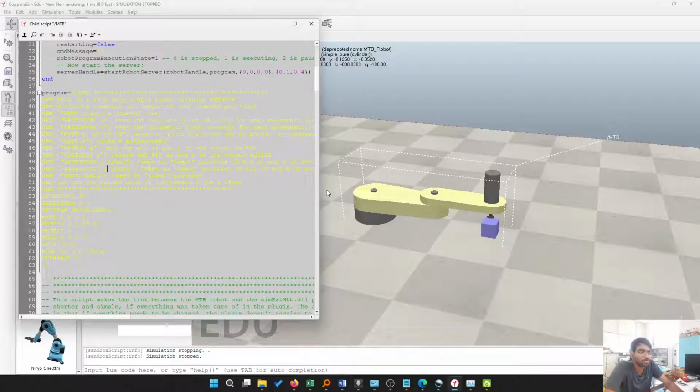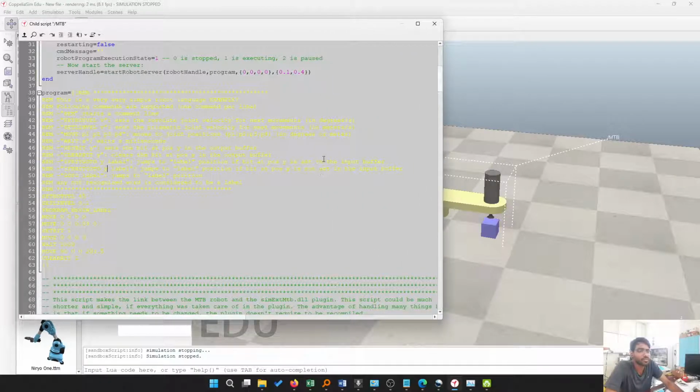If you see over here, there's this IF BIT GOTO Y label. It goes to a particular label when the input buffer has a particular value. So we have to write a value to this input buffer whenever the proximity sensor sees something. Let's move to that part. I'll show how to integrate a proximity sensor with this and do it further.